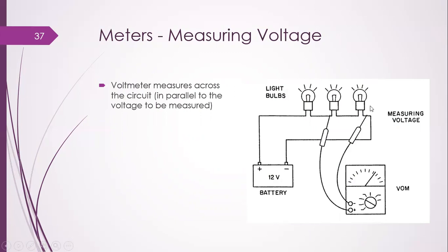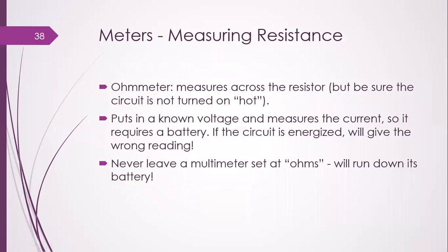Imagine that these are three resistors connected in series like a load of bulbs. Then if we connect the probes of the multimeter across particular resistances, the resistance would also appear on the resistance scale of the meter, but we need to select it from the selector switch. Then the resistance would be found. So this is the way of measuring resistance, similar to measuring the voltage.